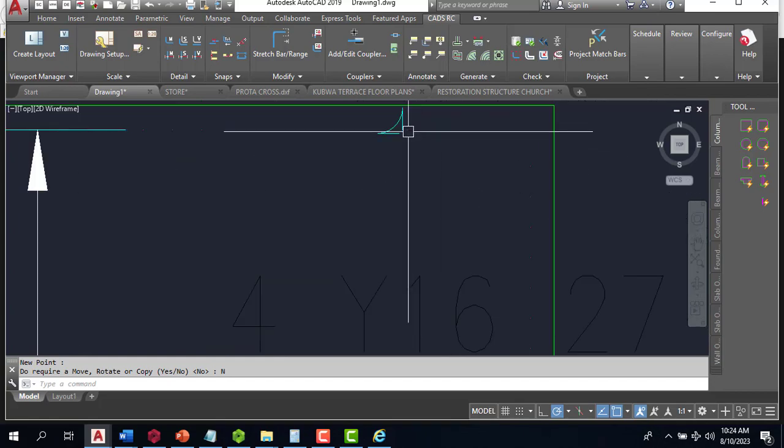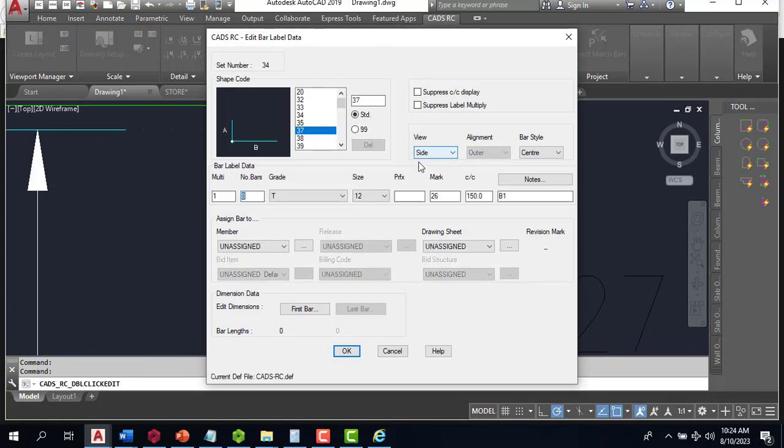So I am going to simply double click on this. The bar I'm supposed to use is bar 38. This is the bar shape. All of these shape codes, over time, as you keep using them, you get to understand. We have all of these shapes, and these are their codes. You can scroll down, you will see you have a lot of shapes. So 38 is what we use for our base. We are going to be using 38, and then I will click on OK.